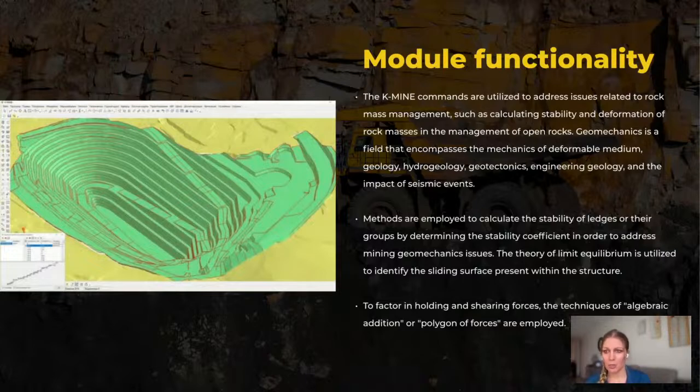And geomechanics in general is a multidisciplinary field, as it includes mechanics of deformable medium, geology, hydrogeology, geotectonics, engineering geology, and seismic events impact. In mining geomechanics, we utilize various methods to determine the slope stability by computing the stability coefficient. One of the useful tools in identifying the sliding surface present within the structure is the theory of limit equilibrium, as it allows to ensure safe and stable mining operations.